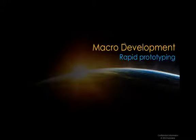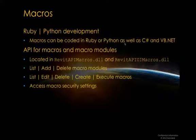We have a number of enhancements for macro development, enabling rapid prototyping. One enhancement is that the SharpDevelop environment now also supports development of macros in Ruby and Python, as well as C# and VB.NET. We have also implemented a new macro API located in new API assemblies, RevitAPIMacros.dll and RevitAPIUIMacros.dll.